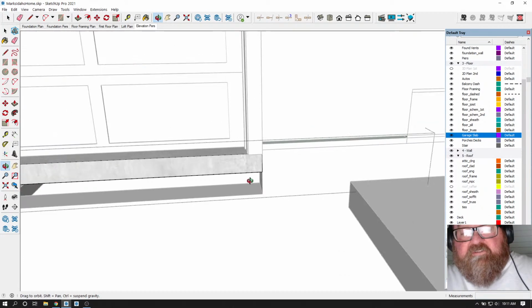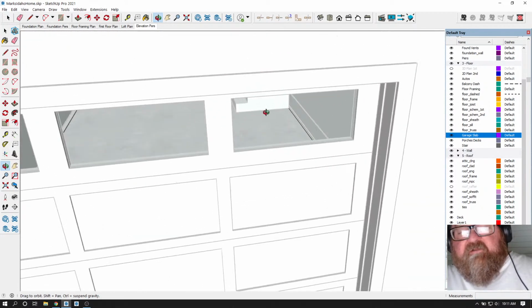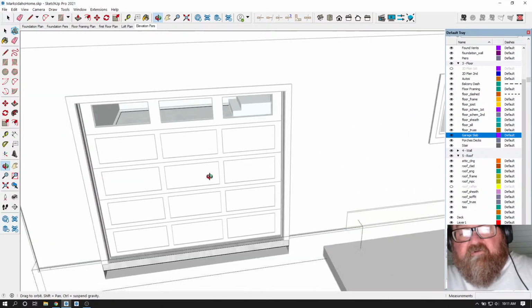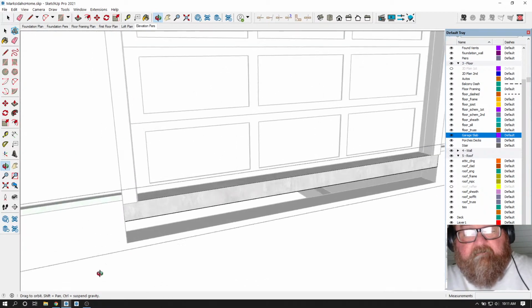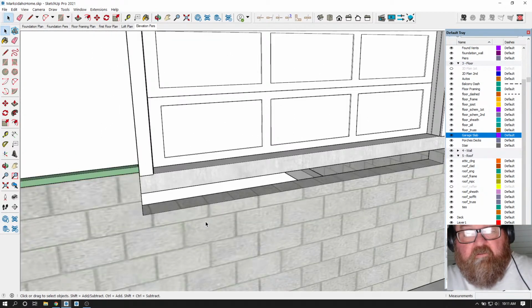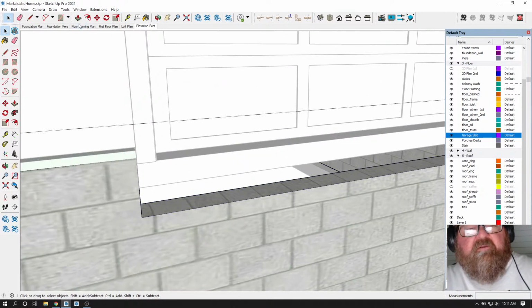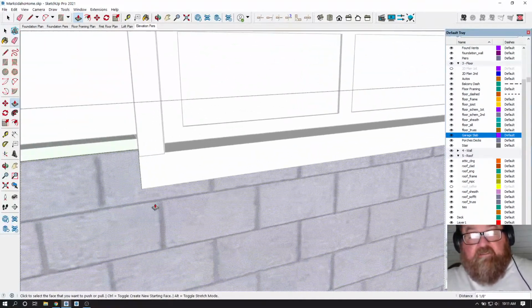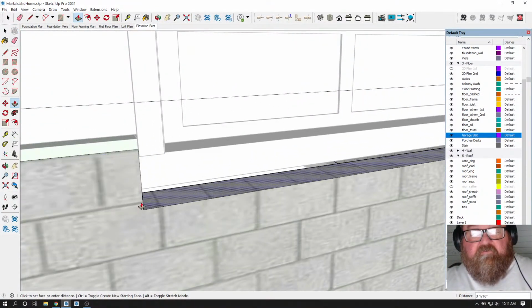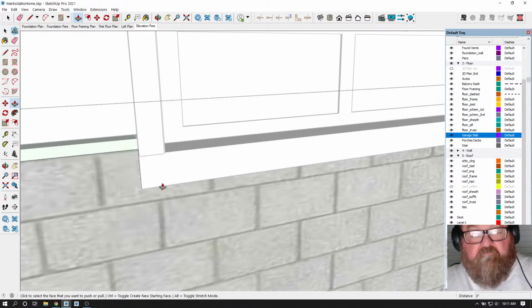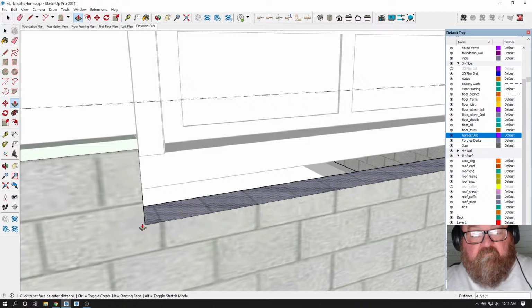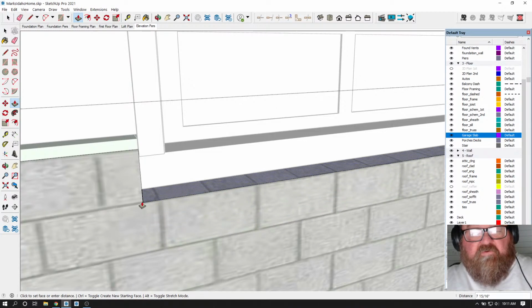And the block was, let's see if I'm at the bottom of that stair now. Yeah, see how the slab's at the bottom of those 2 steps in there? That's where I want it to be. So that means the block will only be cut out for that much. Most likely it'll be cut out to here, and you'll just turn down. It'll be at that course right there.